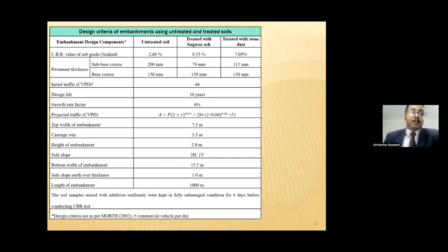For designing the proposed pavement, the project requirements were established by analyzing the soil properties and the dimension of the road, and design parameters such as design life and traffic estimations were considered as per Indian standards technical specification. The embankment trial geometry was finalized following the recommended guidelines available, and this research was attributed to stabilized soil along the stretches of Dipor, the freshwater lake that forms a channel to the Brahmaputra river in Guwahati.